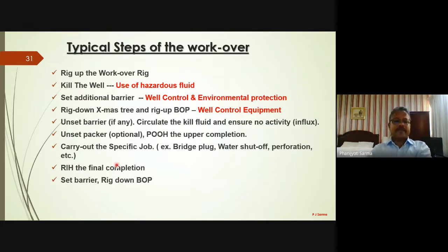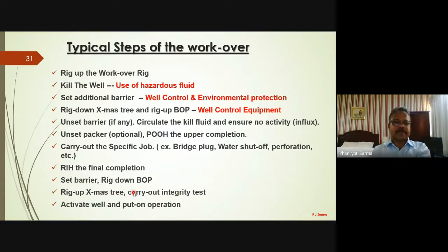And then when you run in hole the final completion, then set the barrier, rig down the BOP, and then rig up the Christmas tree. Once the Christmas tree is placed, then carry out the integrity test of the Christmas tree, pull out this additional barrier, and then activate the well. So these are the typical steps of the workover operation.